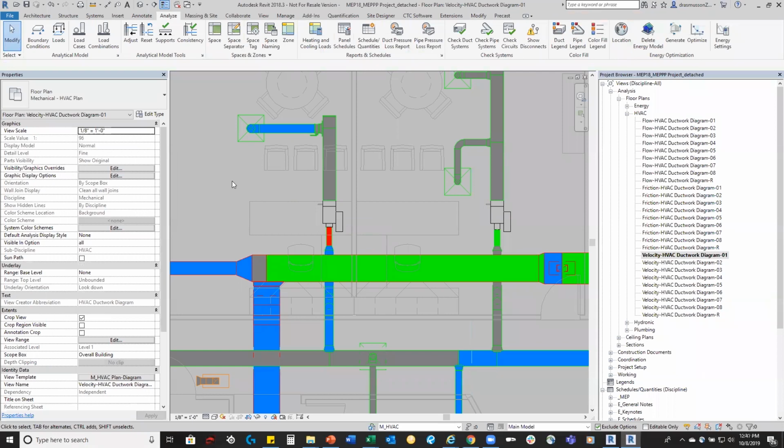Outside of understanding how Revit flow actually works, that it flows backwards like I just explained, the other way of making sure that your device error is being calculated and things are working, guys, is just simply making connections and making the good connections where Revit knows what to do. If Revit doesn't have a connection, or if we're faking something to make it look good on a plan sheet or something like that, we're throwing all the ROI capabilities that we have with Revit out the window.